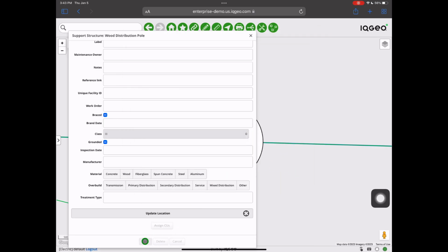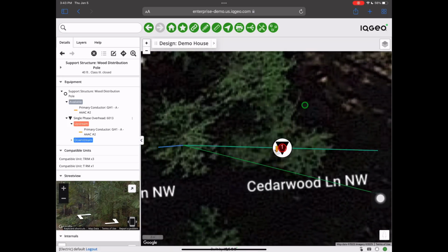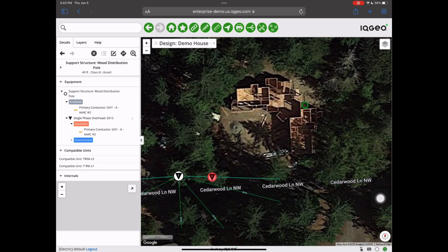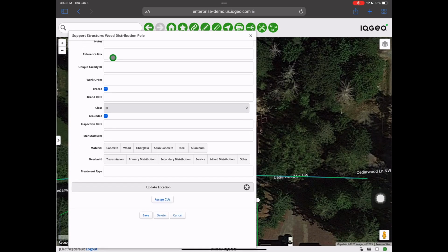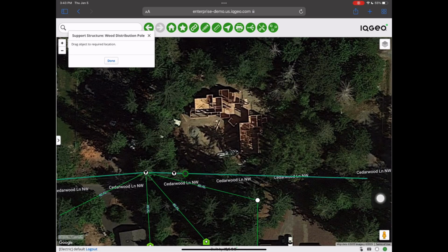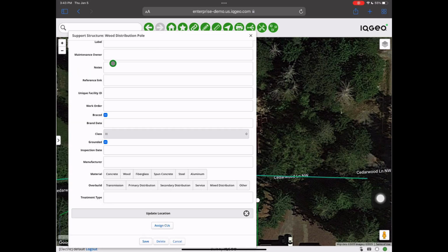I meet the customer while I'm here, and I inspect their conduit trench, which is currently stubbed short of the proposed pole location. They share with me that they've shifted the plans for their new driveway to the east, which allows me to relocate my pole to a better location to avoid tree obstructions and reduce the amount of trimming required.